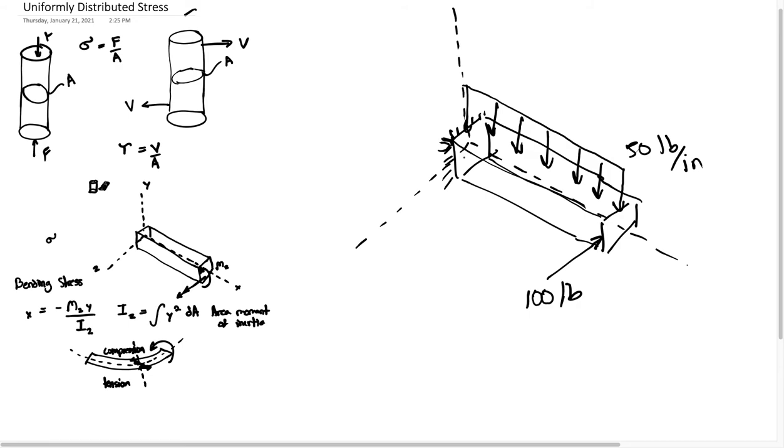So we know it's going to be a point on the wall, where it's attached. And if we're thinking about tension, looking at the uniformly distributed load, the behavior of this beam is going to look somewhat like this, if looking at it from this side. And so the max tension is going to be at this point on top. So we can already say it's going to be somewhere up here on the top.